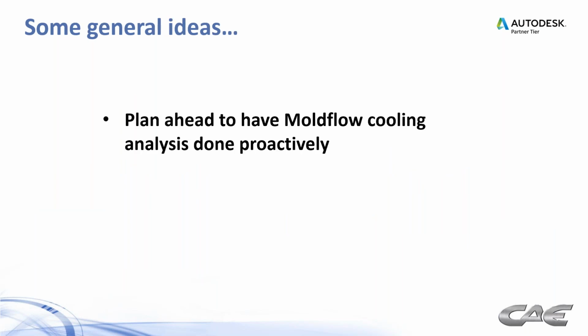So here's some general ideas. Make sure you plan ahead to have Moldflow cooling analysis done proactively. Don't wait till you're ready to cut steel on a mold to do this. By then it's often too late, the clock's ticking. So make this part of your everyday activity when it comes to designing and manufacturing molds.